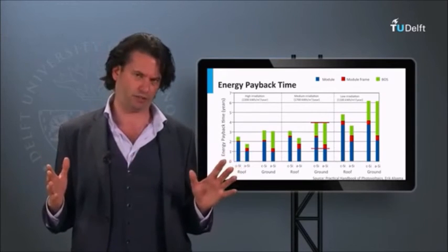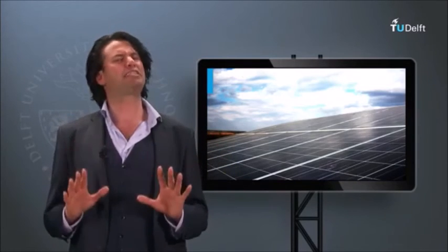In summary, it can be seen how the energy payback time is much lesser than the PV module's lifetimes, which can be as high as 25 to 30 years. For the system discussed in the previous graph, the energy yield ratios are also anywhere between 4 and 10. Thus it can be said that the energy invested in the PV system manufacture is paid back several times over during its lifetime.